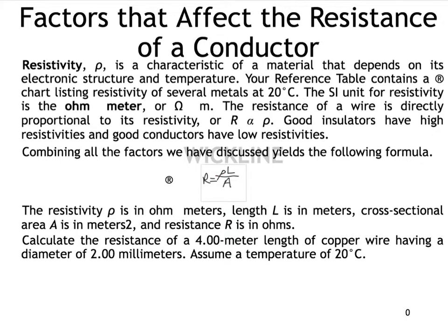And you can see that here in the equation. Here's resistivity. It's symbolized by the Greek letter rho. I know it looks like an italic P, but this is actually a Greek letter. There's a direct relationship between resistivity and resistance, so the larger the resistivity, the larger the resistance. Additionally, the larger the length of the wire, the larger the resistance, but we knew that from the previous slide. We also know that the smaller the area, the more resistance there will be. That's an inverse relationship, because when area goes down, resistance goes up. You could also say that the larger the area, the less resistance, and it's also inverse. So that's just our way of combining all these factors.